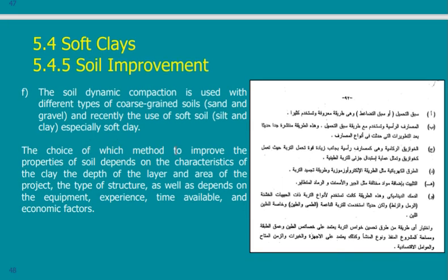Here, the choice of which method to improve the properties of the soil depends on the characteristics of the clay, the depth of the layer, the area of the project, and the type of structure. Each project you study, maybe I tell you that number F is the least important, but maybe in your project it is the only feasible way, because maybe you have the equipment from a previous work nearby, and you have the experience because you have already done this, and you have a very good contractor, and you have all the material that is needed.